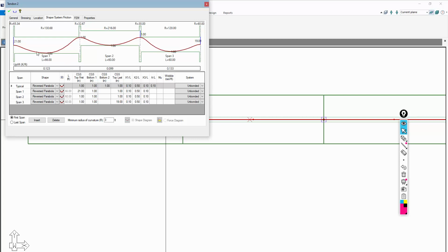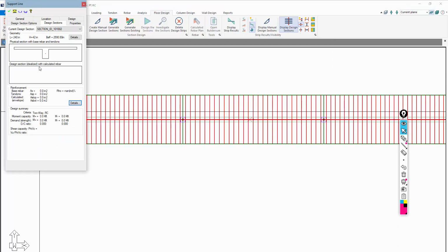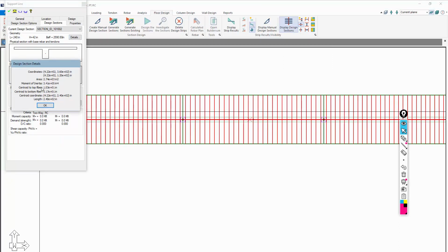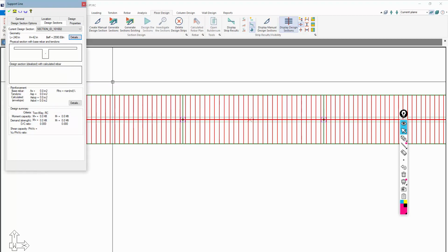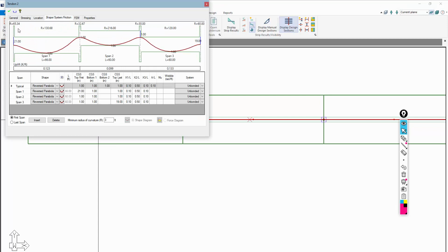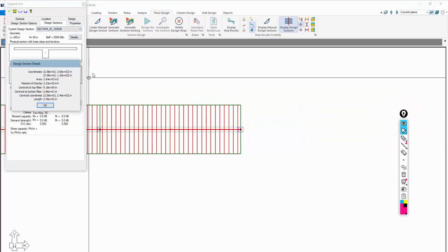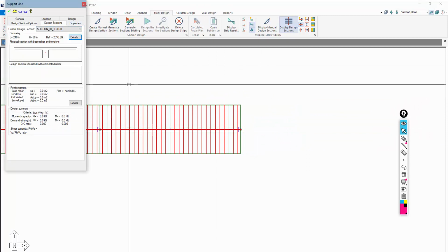Under shape, we're going to dictate the profile. So this anchor point over here, this is actually half the depth of each beam. Now, if we wanted to know what the CG was for the section, we could double click on the design cut, and I could see the centroid to the top fiber is actually 10.3 inches. I'll just round to 10, and so we'll use that for the anchor point. So the user can define where that anchor point is on the end. We'll say instead of 21, it's 10 on this end. Actually, I should have gathered the other number too, because that's a different section. On the opposite end, let's say 9 inches.